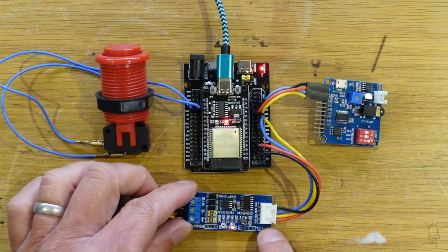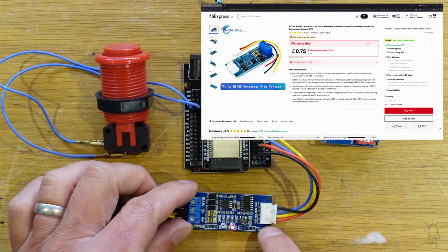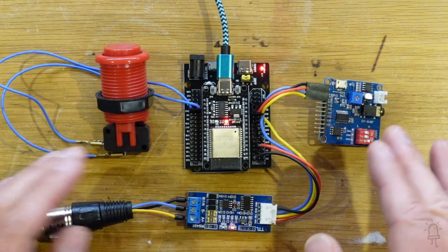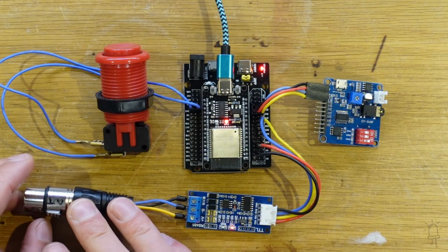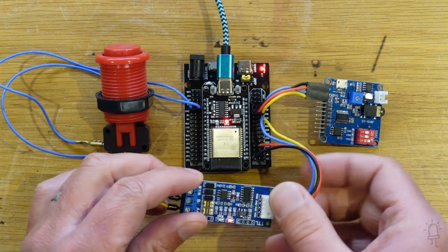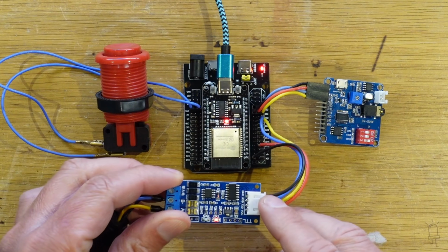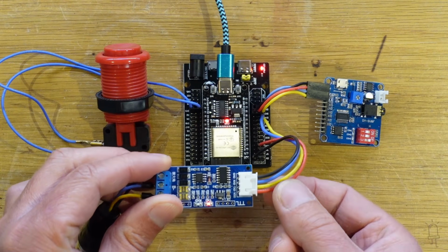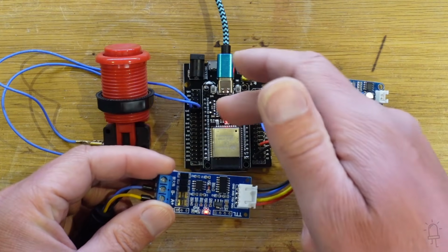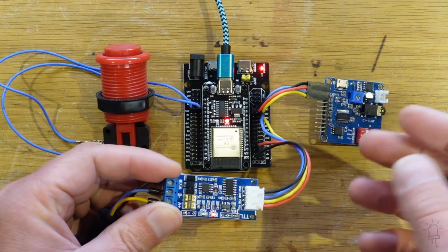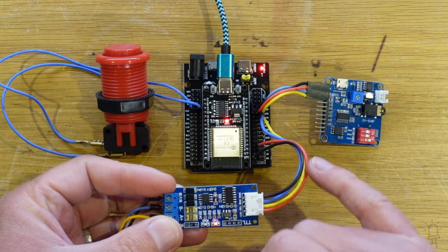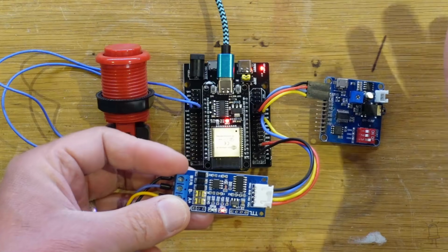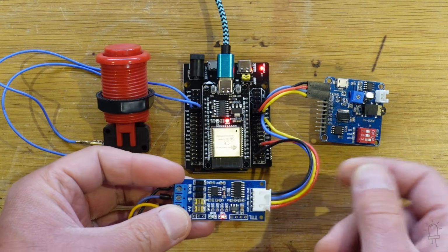Now this is an RS485 transceiver module, and RS485 is the physical networking infrastructure layer on which the DMX protocol is based. So on this side of the module, I've connected GPIO pins to the transmit and receive lines, as well as to ground and to VCC. Now, because I'm using an ESP32 that runs at 3.3 volt logic, I'm supplying 3.3 volts on the VCC line. But if you're using a 5 volt microcontroller, like an Arduino, this will run with 5 volts on VCC just as well.